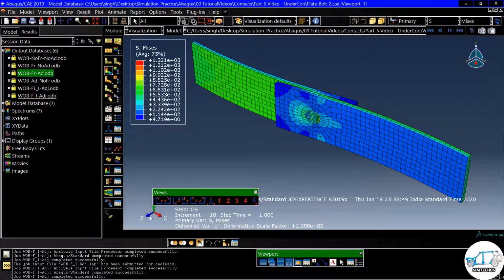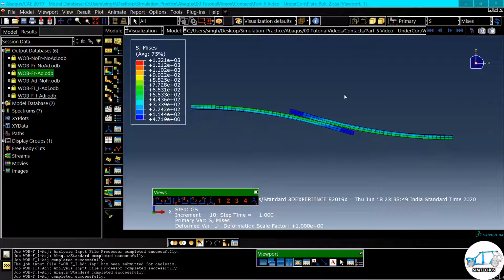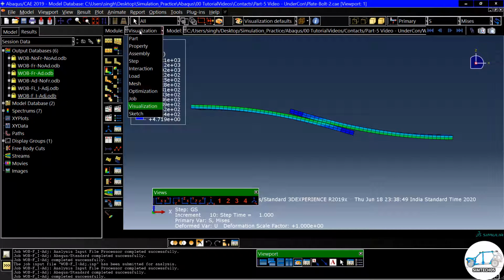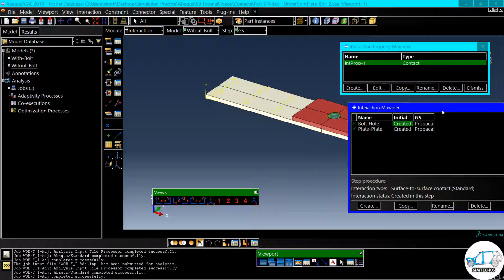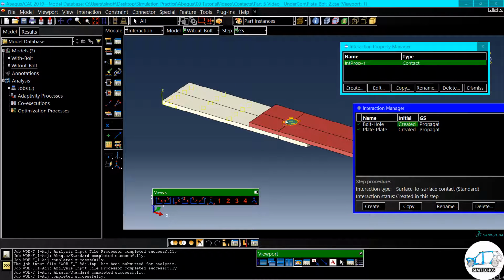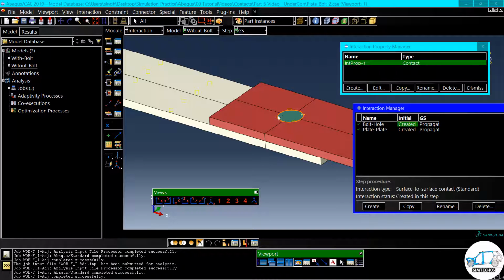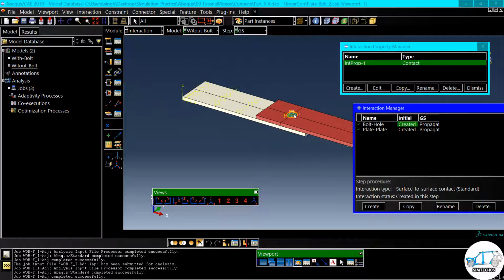Click on displacement result, click on some standard view, and you can see more axial stress as well as bending stress. The reason for the bending stress I already explained. So this is not the only way; we have some more ways to solve the problem. Actually, this type of component does not exist. Even if we have a rivet, we have some head, and due to that head, the free motion of this particular component may be restricted. But I am just telling you, if we have such possibilities for any component, then what adjustment you can do.